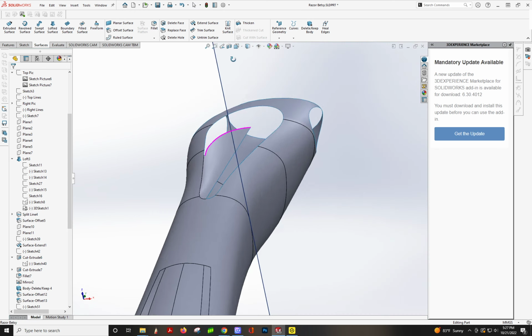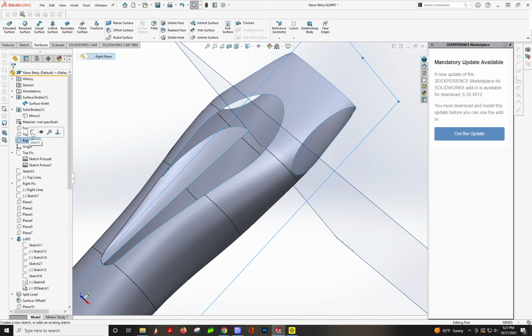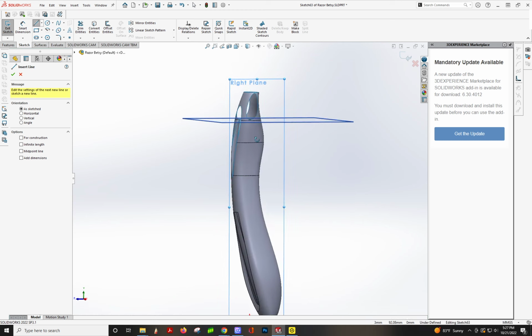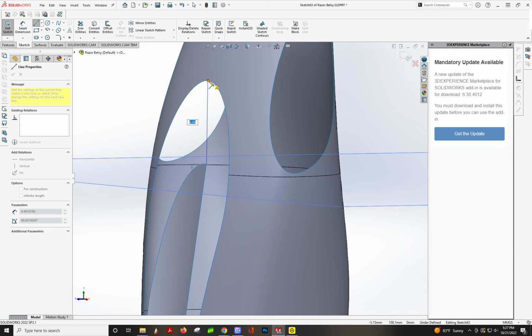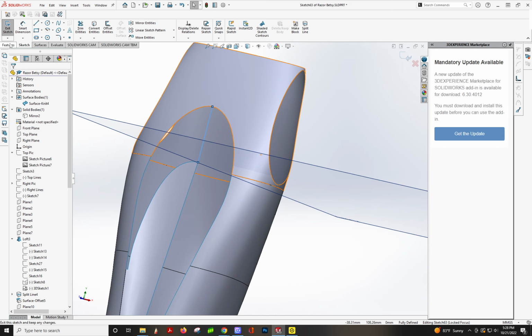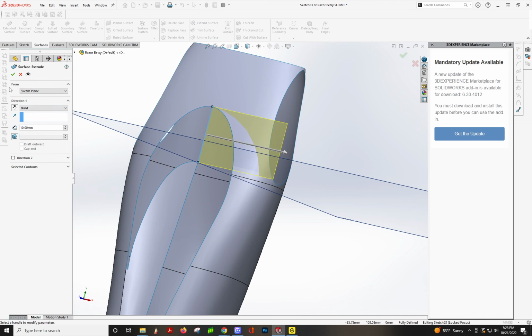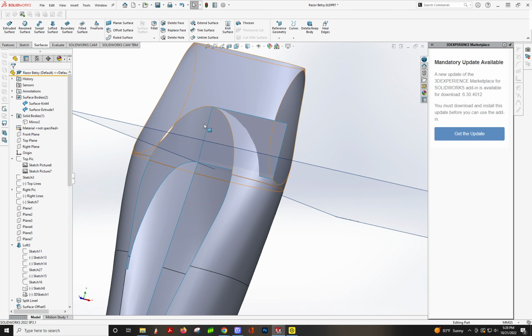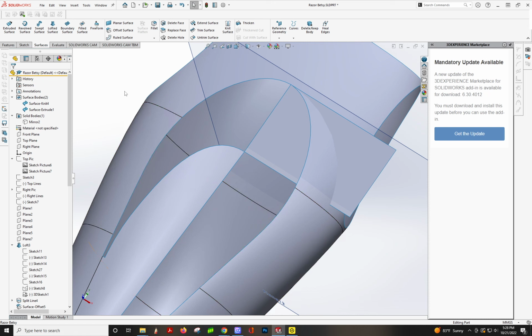Okay, so this is another one where it's just a straight edge chamfer, which is much easier. So on the right plane, sketch here. Perfect. And then we're going to add in a couple of, we'll do this. This is a nice way to go. It's like a little tab that I like to do for boundary surfaces. Then everything, you just have to be tangent to that and everything runs real smooth.